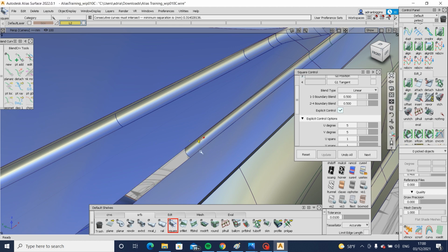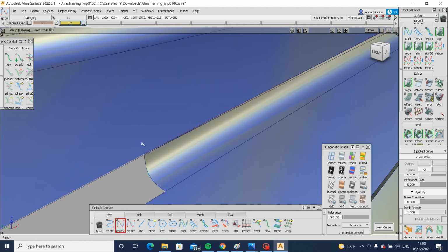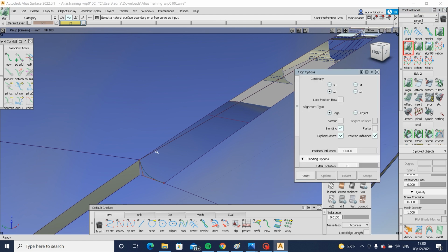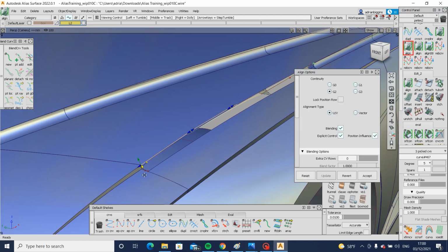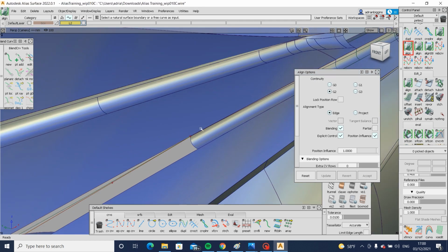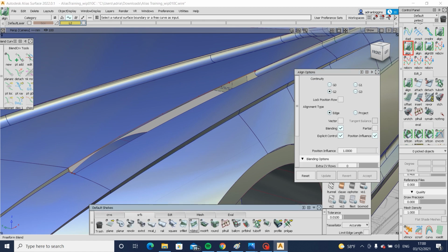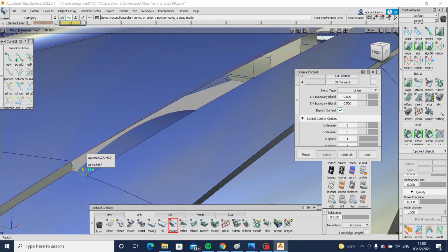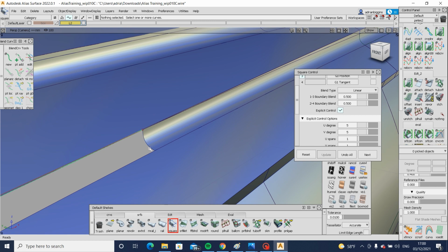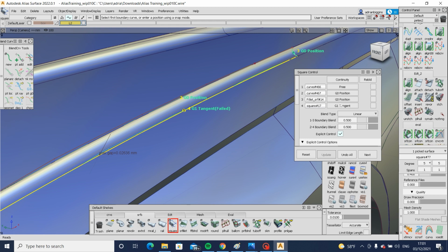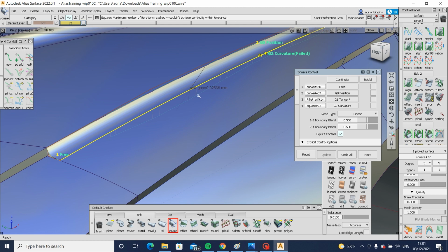No! Yeah, whatever. Right, rebuild a curve to this edge, and this edge. Up that to 5. Curvature align it. This is why it's really important to make sure everything is positional and stays positional, otherwise you then have to end up rebuilding the edges so you can build squares and fillets and everything later on. But I'm used to it now, so I just quickly rebuild an edge with a curve. Right, so number 2's position, 4 we want curvature, 3 we want tangent, and this one's fine.